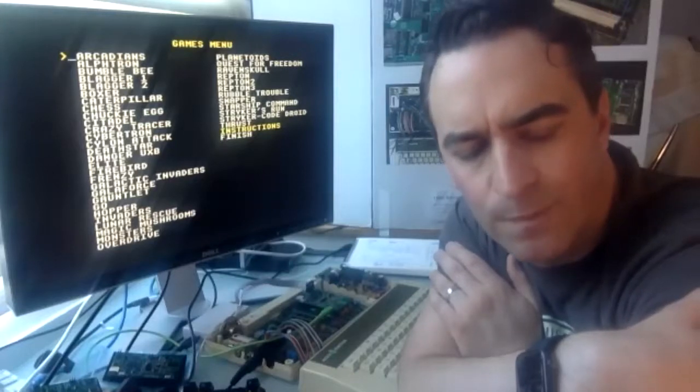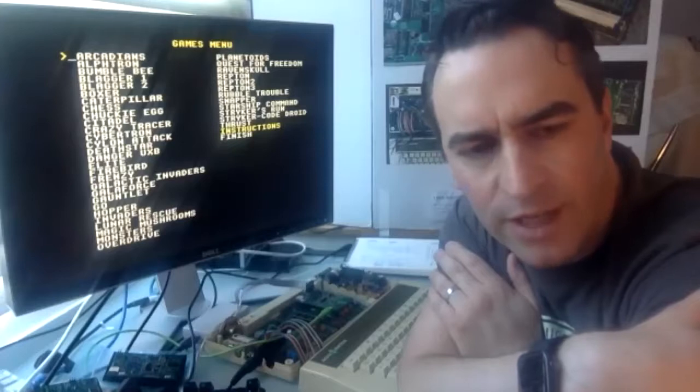Are those auto switching? Yeah, I think they're end-to-end FET things, but I've used them, and I have to say I've not had a single problem with them, other than they won't do CMOS levels, but they do TTL levels really well. And you don't need to tell them which direction the bus is in. And I had the same problem you had a while ago with the bus hold stuff screwing things up, and I've not had anything like that with these.